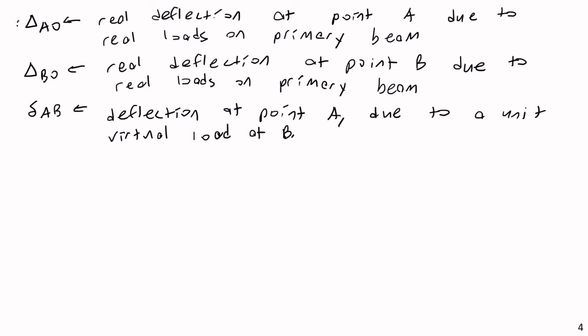So my capital deltas will always refer, at least when I work through this method in this course, to real deformations in the real structure. My lowercase deltas are going to refer to deflections that come from unit loads applied at redundant supports, typically at redundant supports.